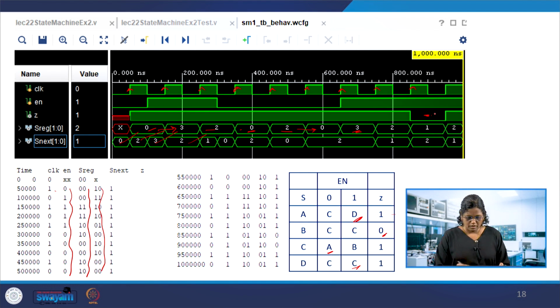So for the given circuit, the state machine module moving from one state to another can be observed from this waveform editor. The design we had done from the digital circuit to the state diagram works in the way it is expected. The Verilog module which we have developed has 3 always blocks, style 1 of the behavioral model.